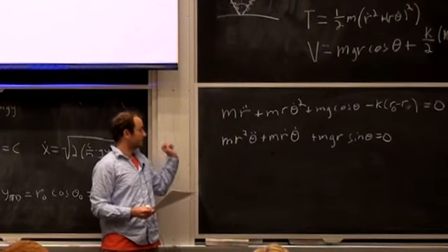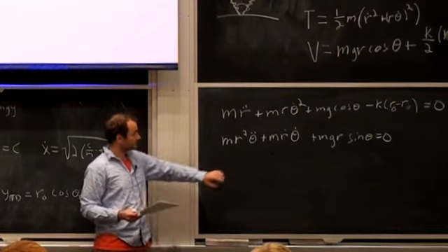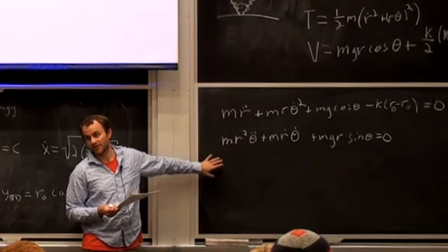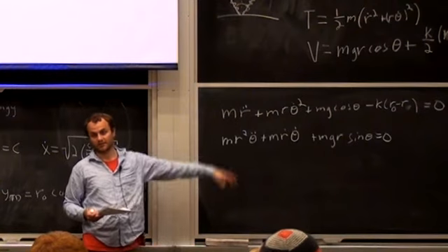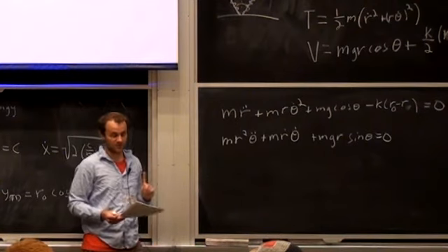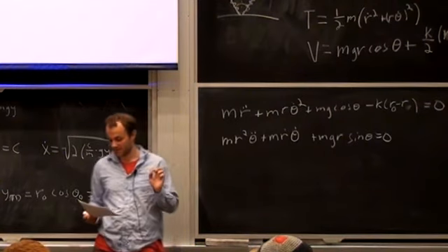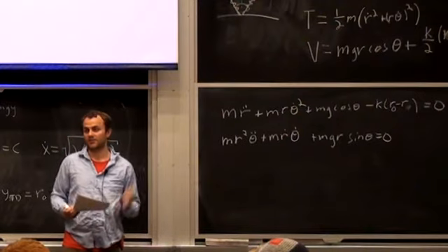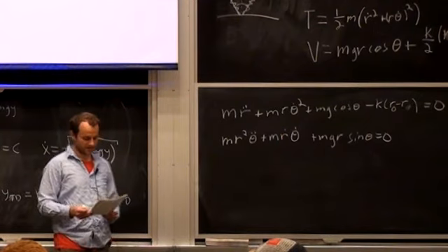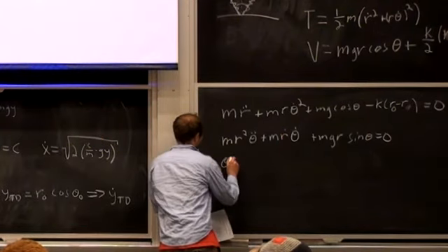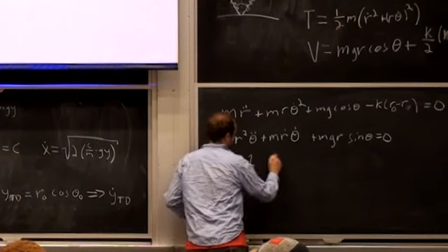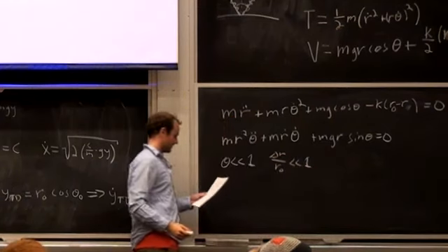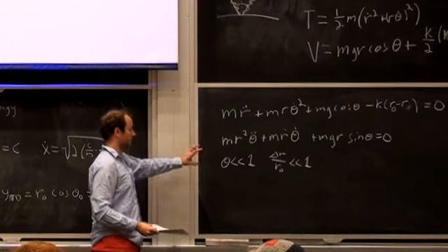And so if you want to get from touchdown to takeoff, you can't get a closed form solution from this. You can simulate pretty easily, obviously, but you don't get the closed form, so you can't get this analytical kind of mapping. But if you use the small angle and small displacement approximation, you can linearize the system, and you can get a closed form solution for this touchdown to takeoff phase. All right? And so that is the assumption that theta is much, much less than 1, and delta r over r naught is much less than 1. And then you can get to a closed form solution.